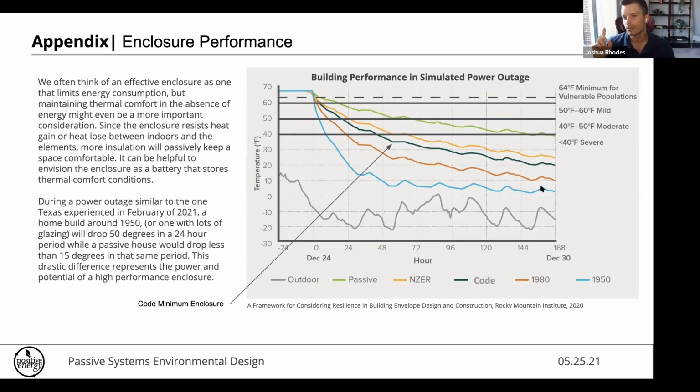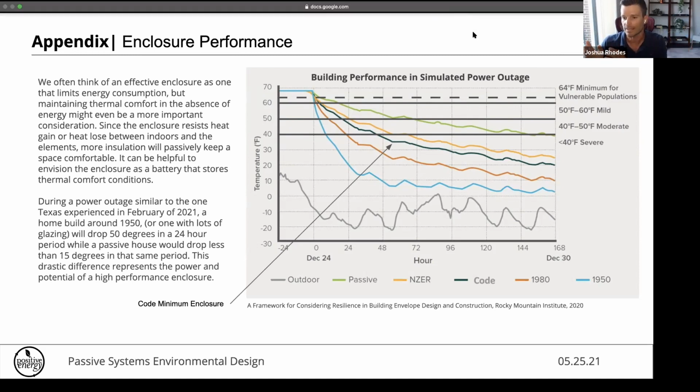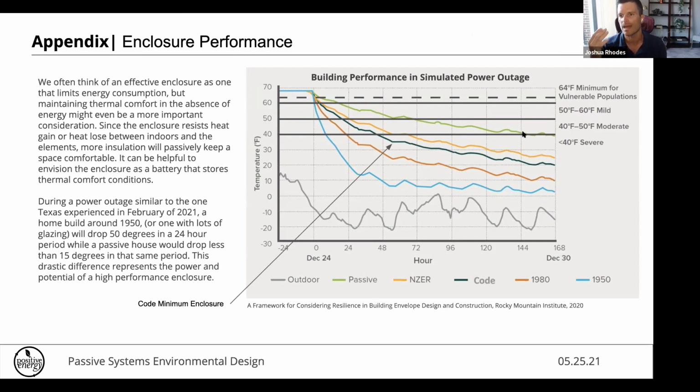Let the electric utility know that you are a critical load, because if you don't let them know you're a critical load, they will turn you off. That's great. Lesson number one, you architects, make sure you're putting that into the operations manual for clients that are in that boat. Definitely one of the things we saw was there were some critical loads that had not told the electric utility that they were critical loads. And so when the electric utility had to cut circuits, they were trying to cut circuits that did not have critical loads. And because they didn't know some existed, they cut some circuits that did have critical load on them. We really saw this in 2011. I thought we learned a lesson, apparently not, because it happened again in February. But that information has to be passed along to the utility so that they know where you are and what you're doing.